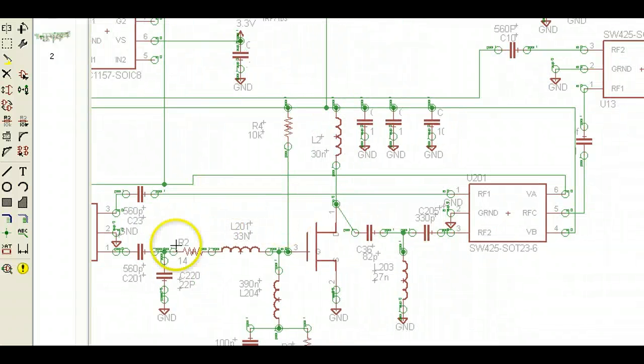So that is this line right here coming out of this switch over to the next switch, which bypasses this amplifier. Again, think of this as a single pole, single throw switch. Remember that it's controlled by these control lines, and these must be orthogonal. If one is high, the other must be low.